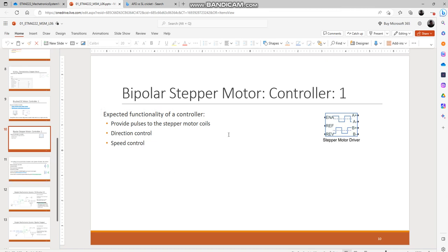So when we move on to developing the models for this exercise, we will be using a stepper motor driver since connecting a power supply to a stepper motor is insufficient. We'll be needing to generate some pulses, and without the stepper motor driver and a signaling source, we won't be able to obtain that pulse required to actuate the stepper motor.